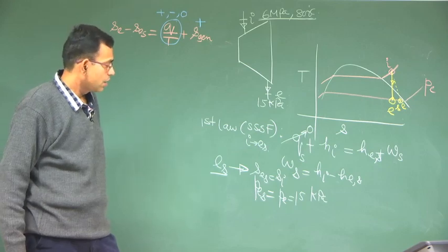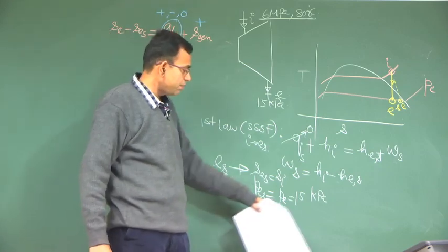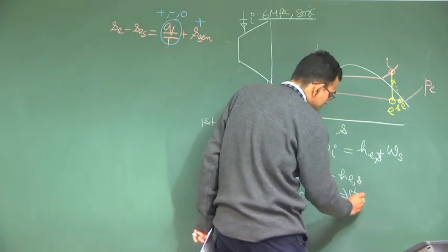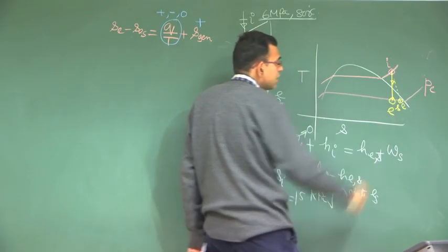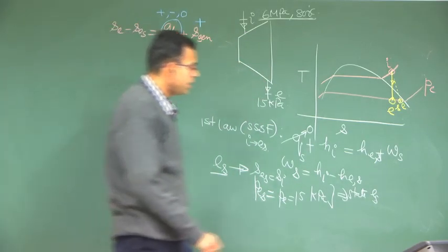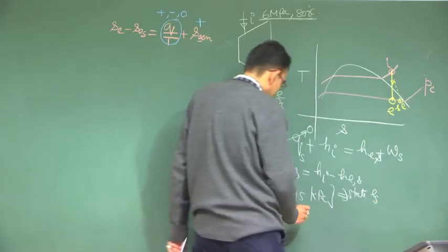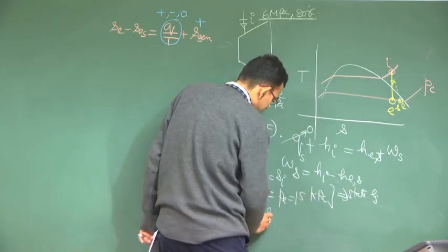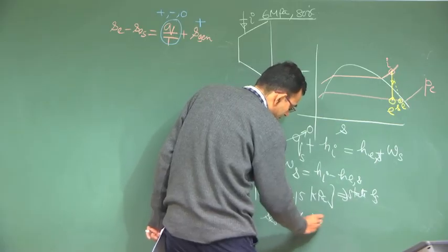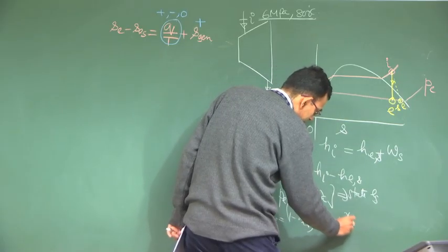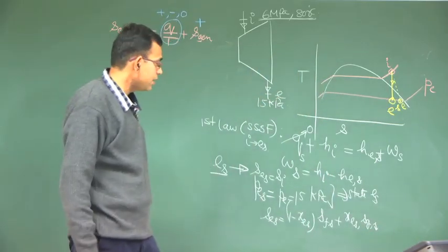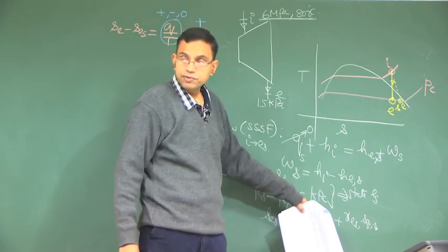Okay. So, SES is equal to SI and PES equal to 15 kPa. This will give you state ES. It will be in the two phase region typically. So, you can find out the quality by setting SES equal to (1 minus XES) into SFS plus XES into SGS, where SF and SG are at 15 kPa.